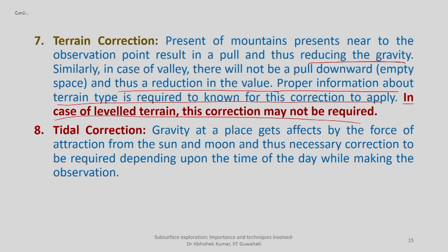Tidal correction, as I mentioned here: because of the force of attraction from the moon as well as the sun, there will always be tides. So depending upon what time of the day you are measuring and what the position of those tides is, you can apply a suitable correction if it is required.